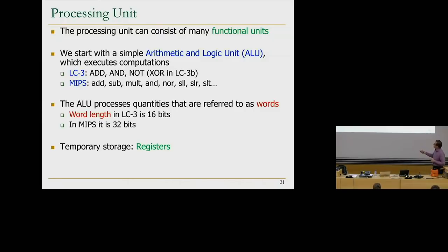So we're going to see temporary storage registers. The registers are temporary storage that the processing unit has to store some values to operate on. You don't always want to go to memory because memory is slow. You want to operate on what are called registers. This is a small file, the register file. We saw the registers earlier. You build multiple of those, and then you move the data from memory into the registers, and then you bring the data from the registers into the arithmetic logic unit, and then do the operation.